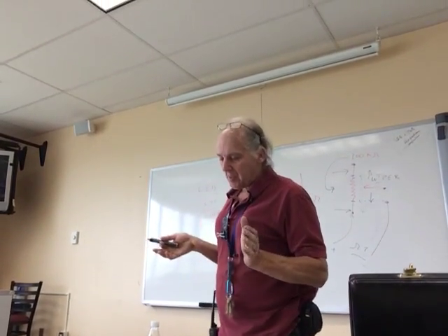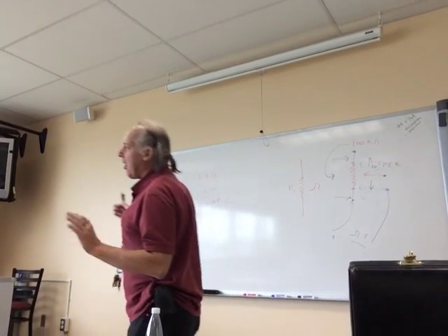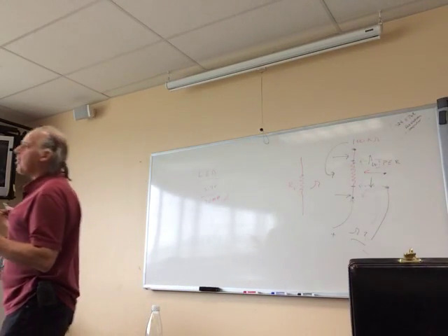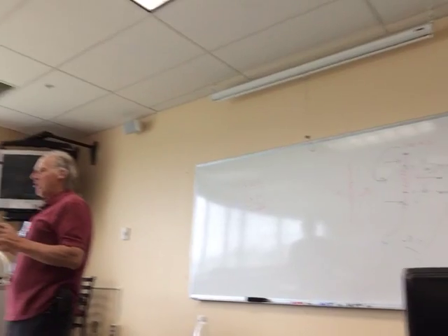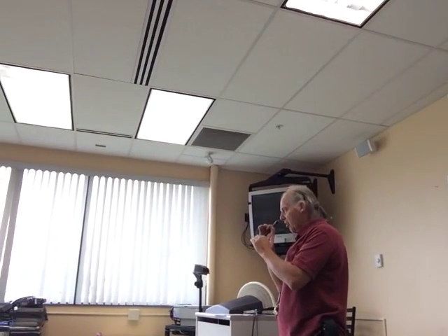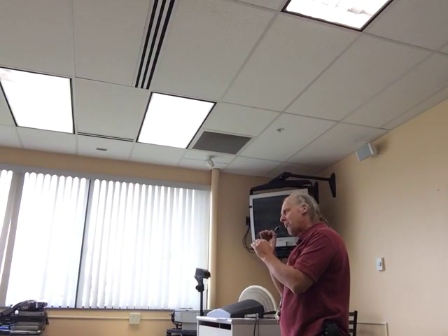What if it was like 100 or a million or a 10 million ohm resistor, a 10 mega ohm resistor? Well, now it's bias. Is there a little current? Yeah, a little tiny bit, but it's pretty negligible. So then a voltage divider works really well to bias that circuit. Okay. All right.